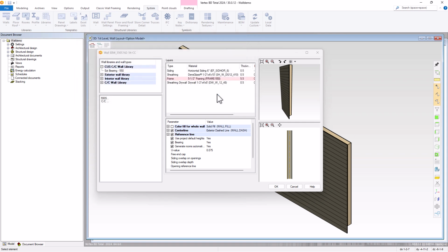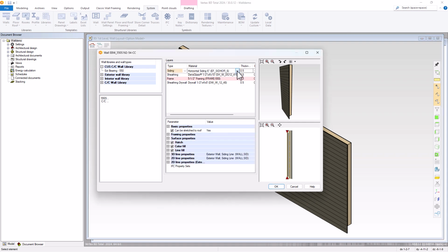You'll notice that the wall type icon in the lower left pane is missing. It will update after reopening the Properties window. We now have a new custom wall type. Though we still have some changes to make to the layers, we will come back to the wall type, edit the layers, and apply a new wall frame tool after we create the other items.